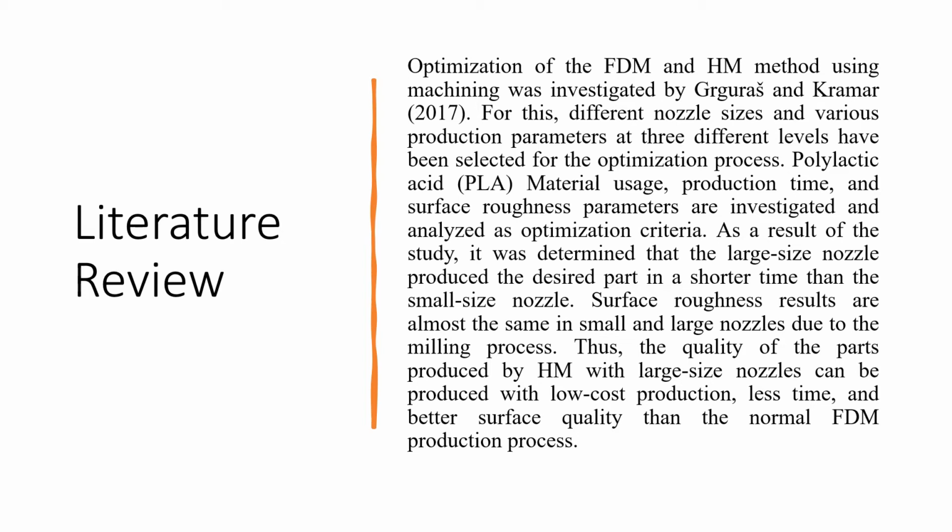Surface roughness results are almost the same in small and large nozzles due to the milling process. Thus, parts produced by HM with large size nozzles can be produced with low-cost production, less time, and better surface quality than the normal FDM production process.